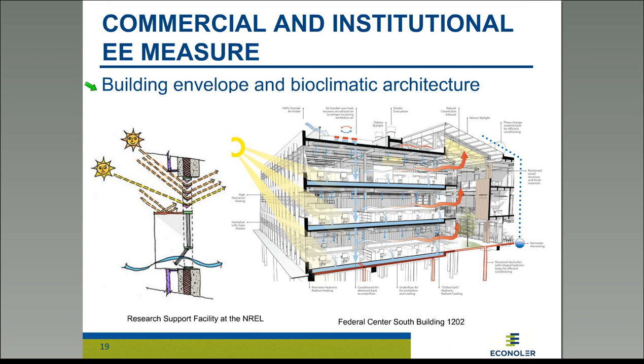And you see that one of the principles that is applied is to try to optimize as much as possible the natural resource. So in this case here, we want to avoid part of the sun energy during the summer when the sun is higher on the horizon, and we want to maximize the solar heat gain during the winter period. You can also proceed with a natural infiltration approach to this kind of project.